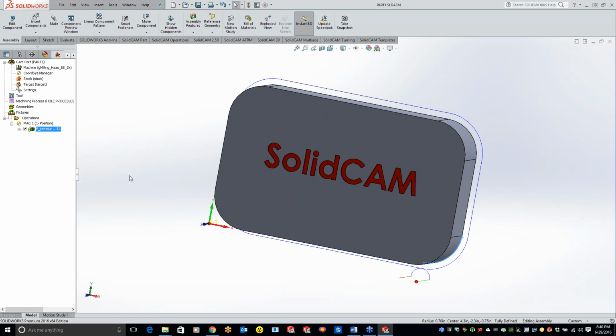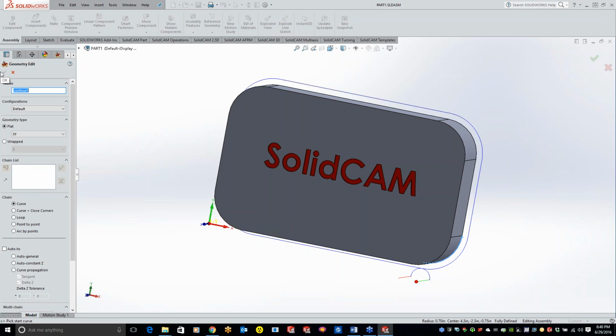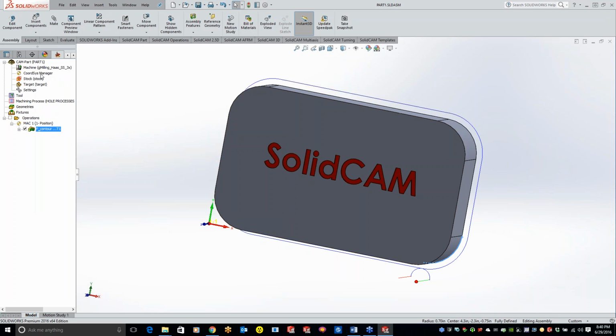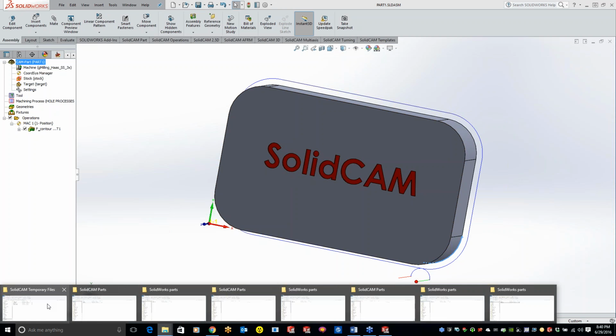Technically, in SolidCAM there is no save button, but every time you click the green check mark, that is saving. If you click Save and Calculate, so you can update your toolpath, that is automatically saving. If you come in here and hit the green check mark to get out, that is automatically saving. So to answer the question, there is no save button. Everything is being saved live in this temporary folder right here.